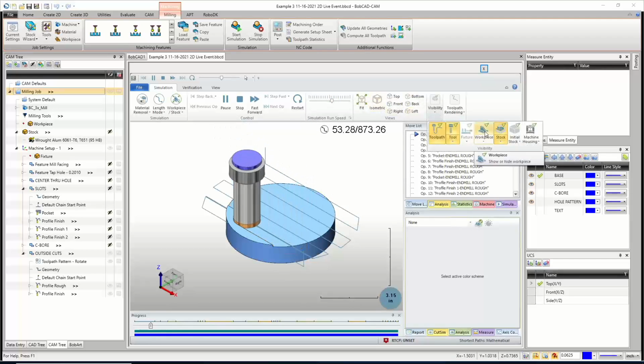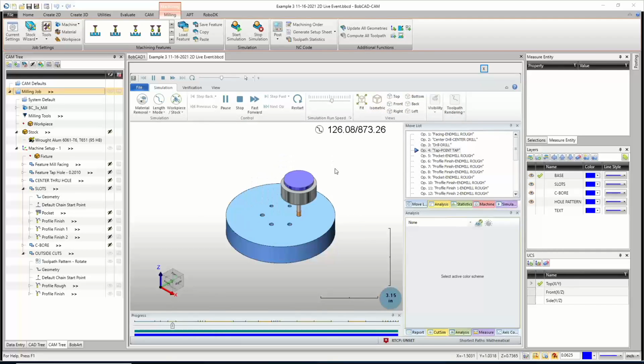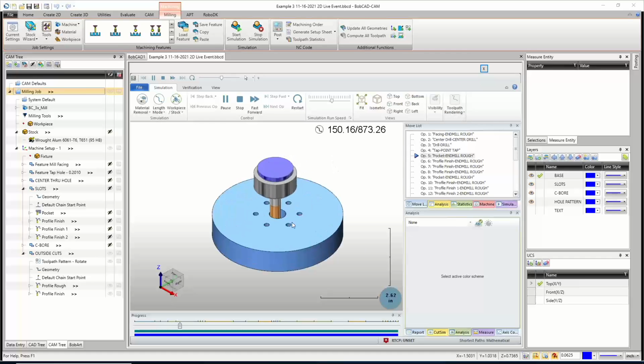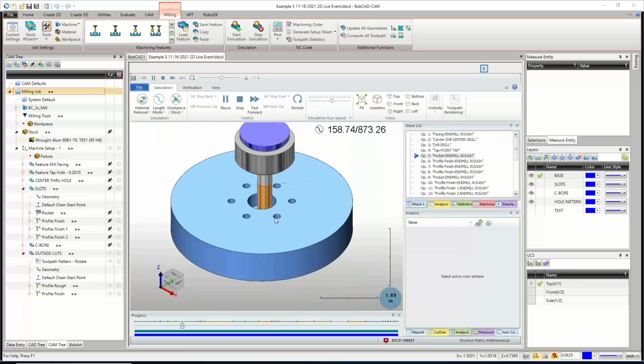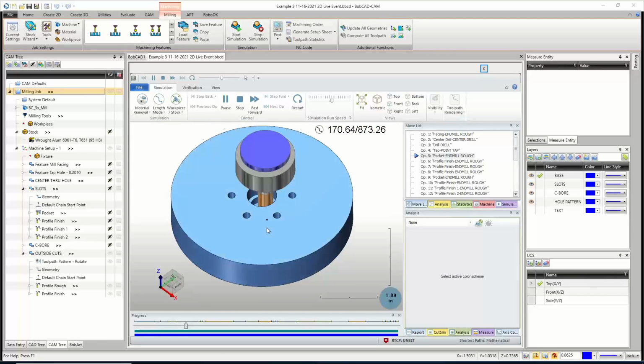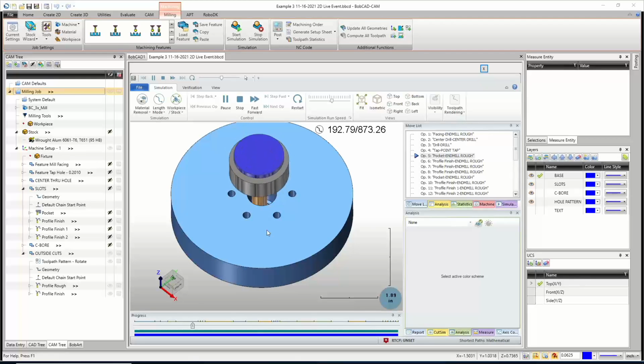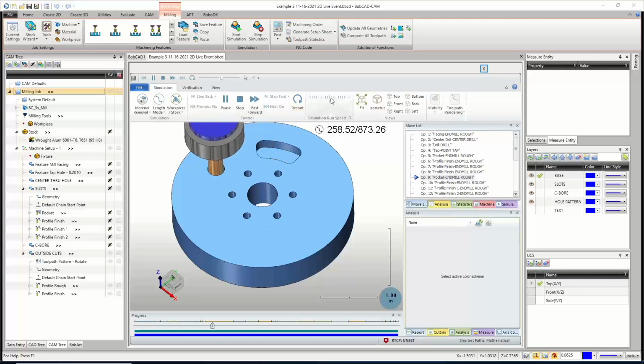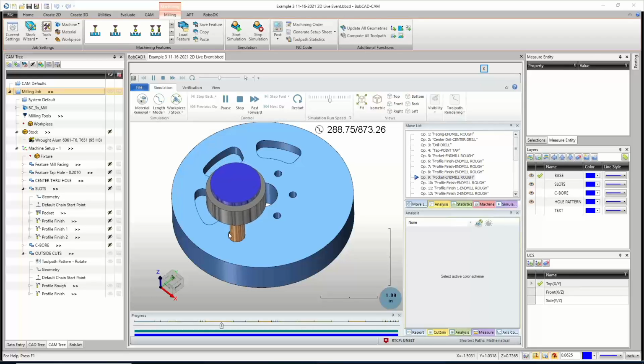I'm just going to hide the toolpath. There we go. Center drill. We should see, we'll wait till we're done. There's our spiral down, and then we're going to open it up when we get down to there. There's that 200 thousandths. Here's going to be my little spring passes. There's my 1/16 inch pockets. Man, it's cruising. I can't keep up. Right in the middle. There we go. So there's that spiral down. That's the new 1/16. Or we could have kept it at that ramp. That's what we would have tried.